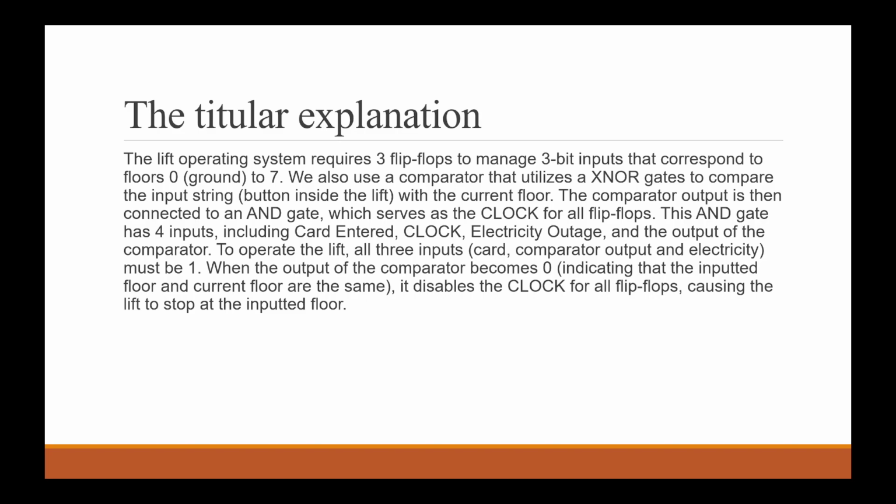For the technical explanation, the lift operating system requires three flip-flops to manage 3-bit inputs that correspond to floor 0, or ground floor, to 7. We also use a comparator that utilizes XNOR gates to compare the string inputs, the button inside the lift, with the current floor. The comparator output is then connected to an AND gate, which serves as a clock for all of our flip-flops.